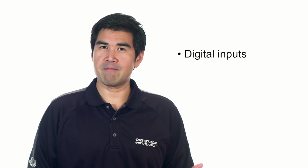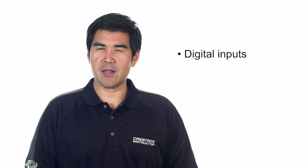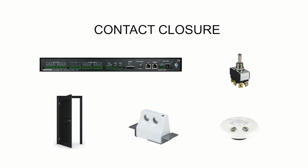Control processors also have digital inputs. There are two types of digital inputs depending on the processor. This information can be found in the processor specifications. The first type is a basic digital input. Using the contact closure input allows the processor to be aware if something has changed, such as a door contact in a partitioned room or a motion sensor.